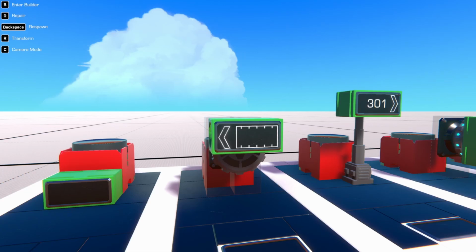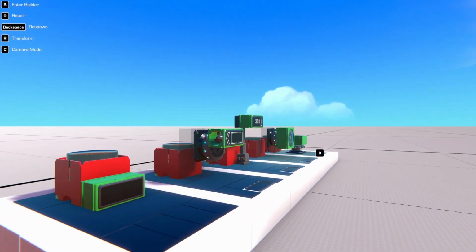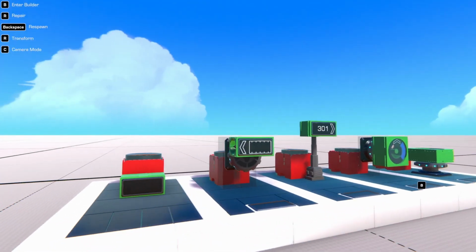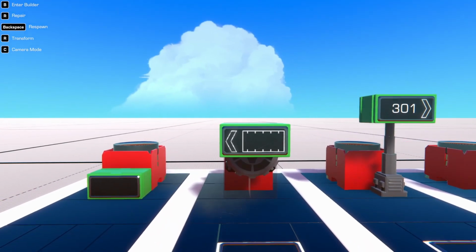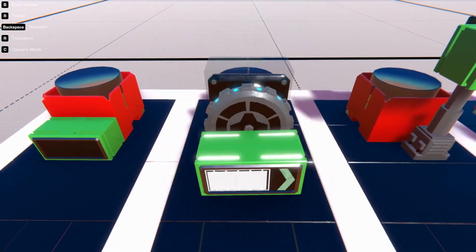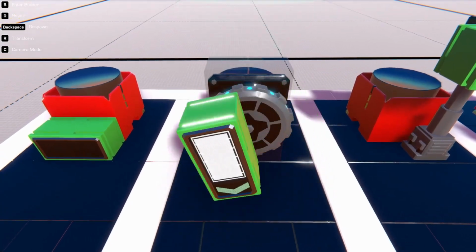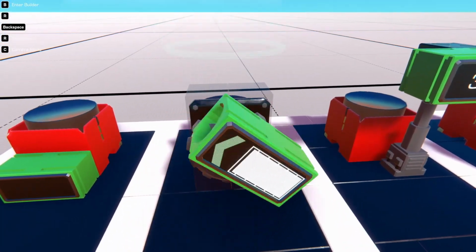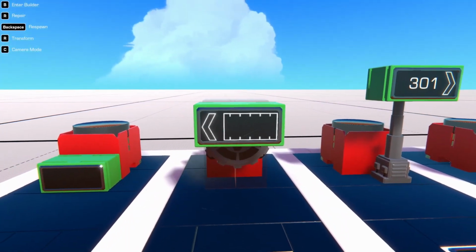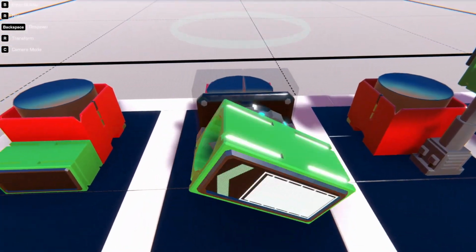This is not measuring angular velocity. It measures linear velocity in the direction of the propeller in the front. So if it's moving in the opposite direction that I'm going to move it, it will not do anything. But as you can see, I'm spinning it 2.2 kilometers an hour directional, and it turns it on because it has reached the threshold. If I stop spinning it, it no longer has an output.